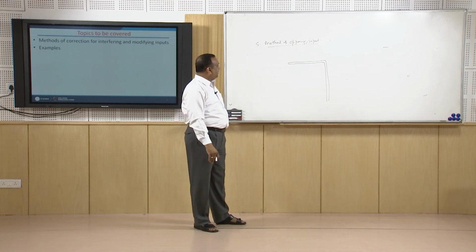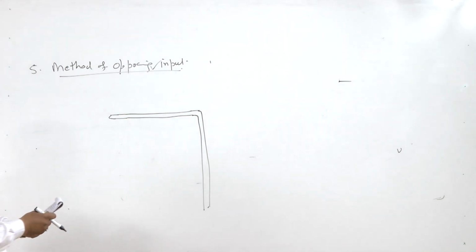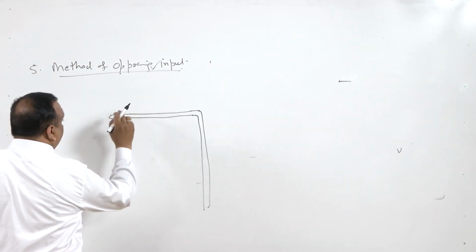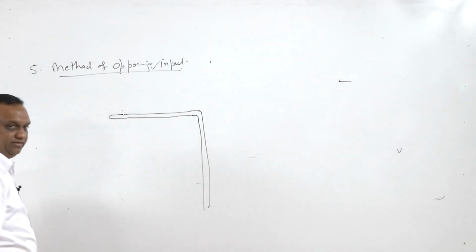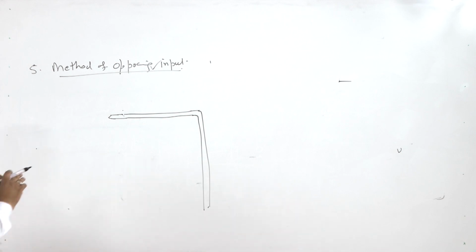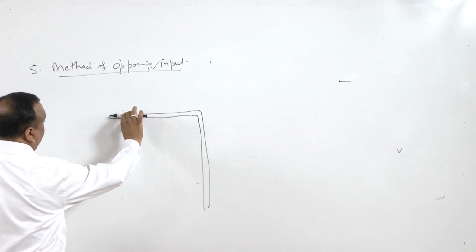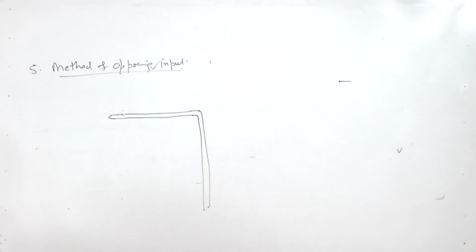Leading edge is the stagnation point, and it is observed when the free stream passes over this probe, right? The static pressure has to be measured from here. There is a hole here, from where you can measure the static pressure, and here we will get the stagnation pressure. So when the flow stream passes over this probe, the velocity here increases, which reduces the static pressure. There are 2 points. One is the nose, where we get stagnation pressure, and another place is where we measure the static pressure, and there is error incurred because the velocity of the stream is higher than normal due to intrusion of this static pressure measuring tube, resulting in a dip of pressure at this point, right?